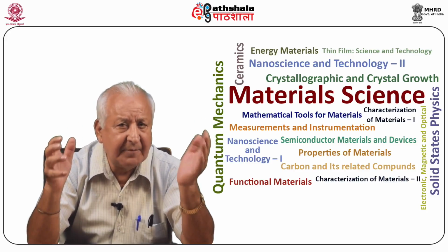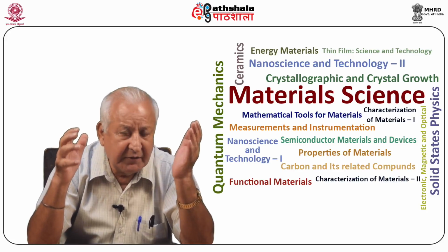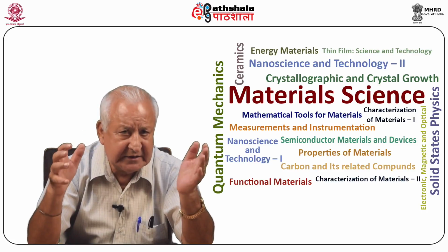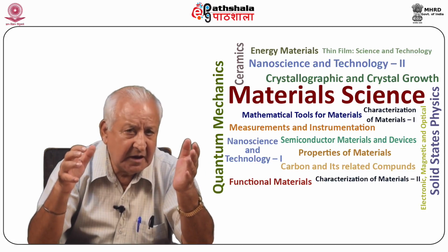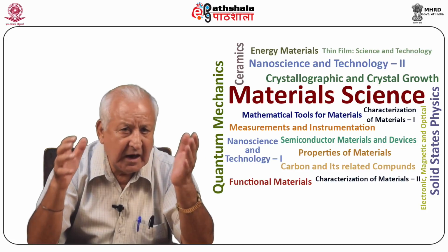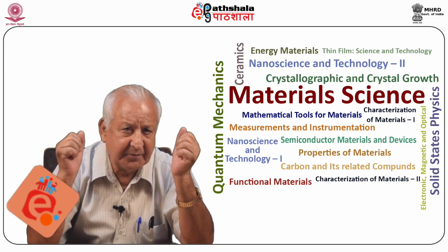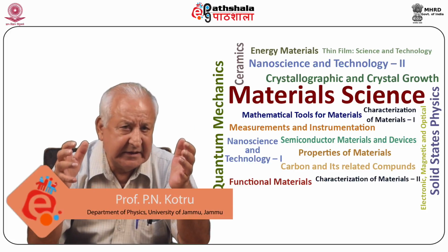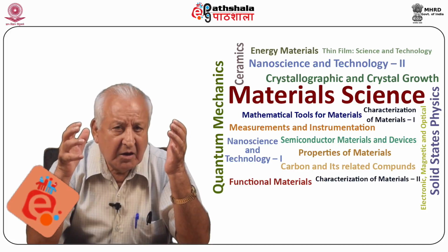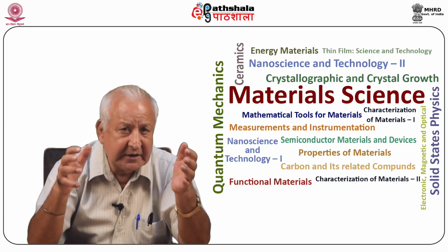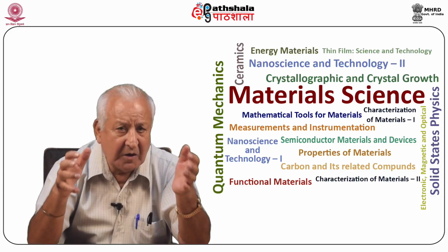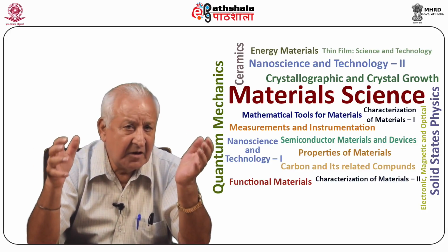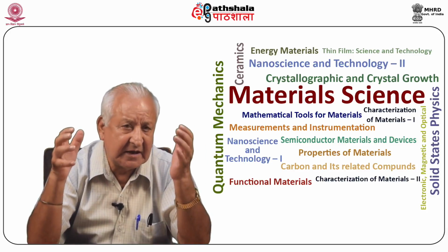Basic background of vapor phase growth, giving description of some fundamentals regarding important techniques like growth by sublimation, growth by chemical reaction, and transfer technique is described. Growth from solid state involving annealing techniques, namely annealing, zone heating, sintering, and hot pressing, is explained. Layer growth from solid phase, also known as solid state epitaxy, is explained.